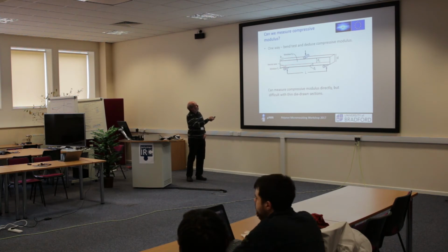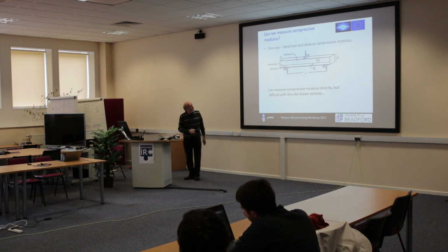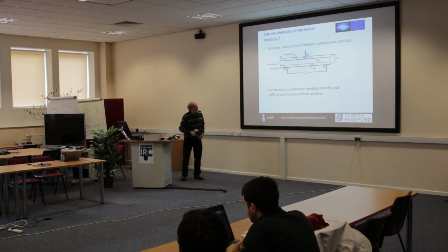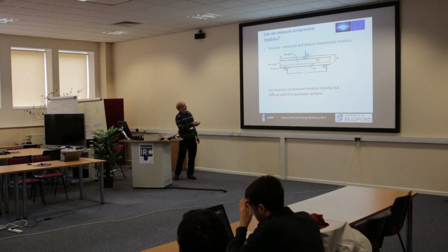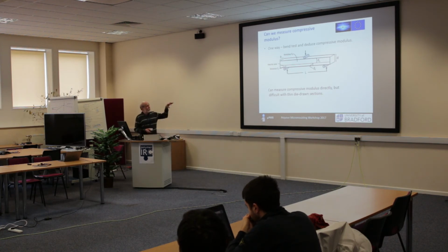The top zone here is in compression, the bottom zone in tension, and you can generalize the theory of bending, so you've got different moduli in tension and compression. It all works. The neutral zone is no longer in the center. The analysis is elementary. And of course, anything you do here, you can check out with finite elements. It will be slightly wrong because it's using elementary beam theory and it's also got anisotropic material in there.